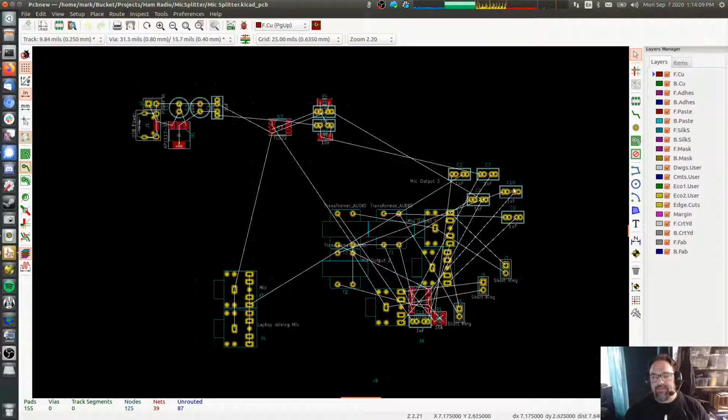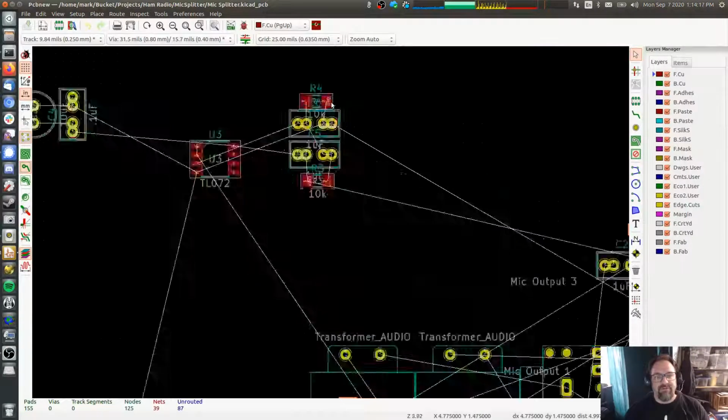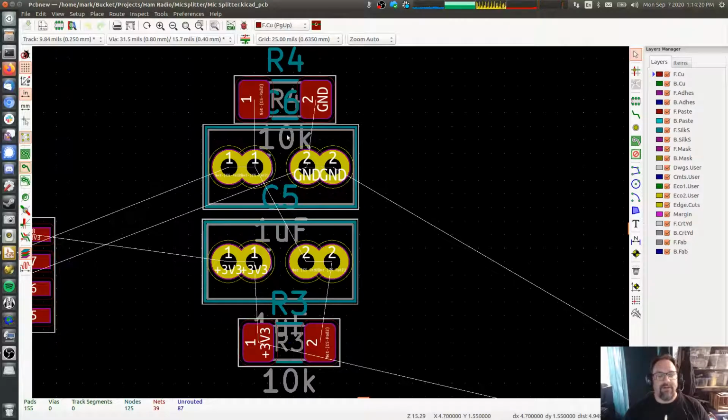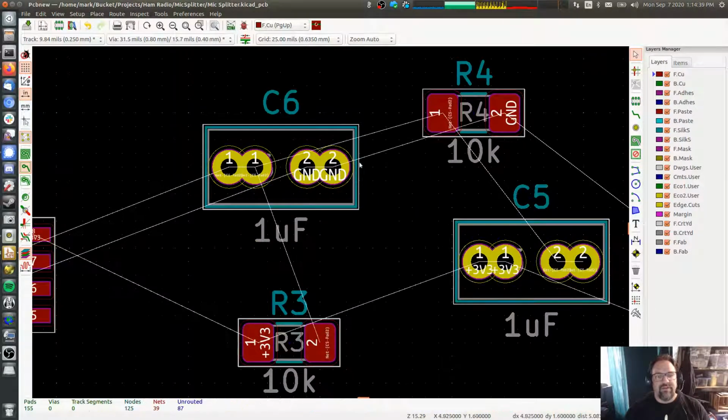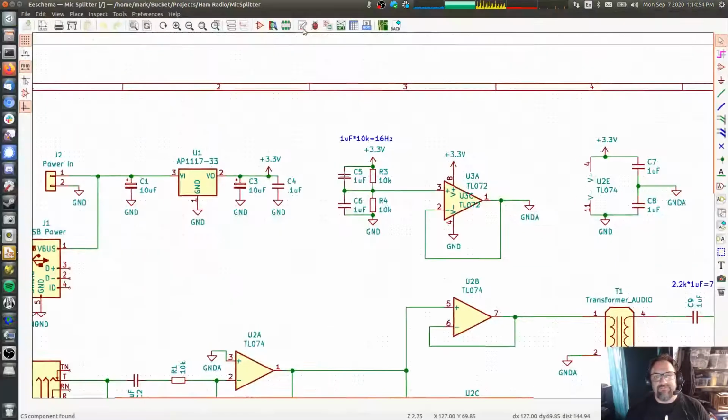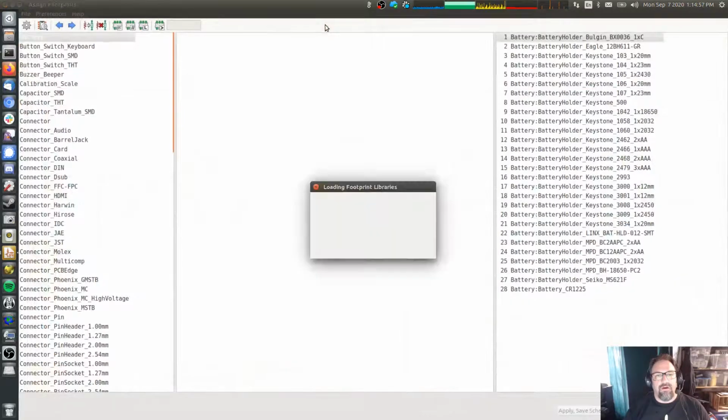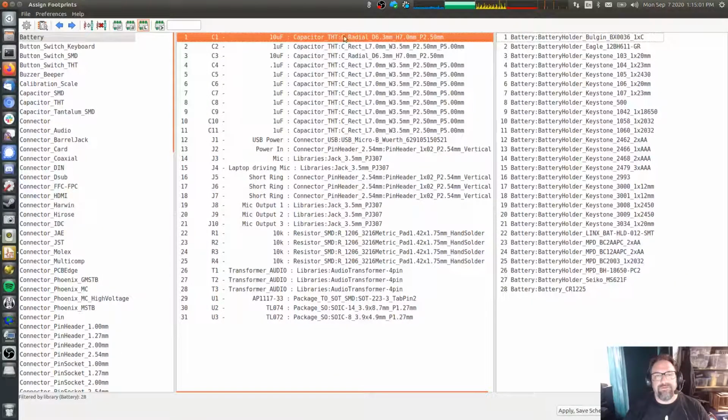You know what? I'm looking at these capacitors, and I want to swap those out. So these capacitors, the physical outline for this is meant to take either a 0.1 spaced or maybe a 0.2 spaced capacitor and a 0.3 spaced capacitor. So it could use capacitors of many different sizes. It gives you a lot of options when selecting components, but it makes layout harder because you can't fit a trace between those two. So I want capacitors that I'm going to be able to fit a trace between, so I'm going to go back over and change that. I was working on a different board this morning and I ran into that problem, and so I want to learn from those mistakes.